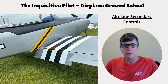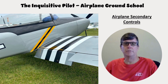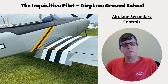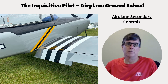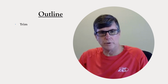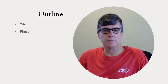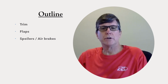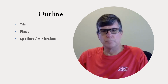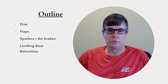During your check ride, you'll be expected to correctly use whatever secondary controls are present in the aircraft that you're using. As you progress as a pilot and you fly different aircraft, you'll need to know how to use additional types of secondary controls. Trim is used to relieve control pressures on the primary controls. Flaps improve the wing's performance at low airspeeds. Spoilers, sometimes called air brakes, are used in aircraft with very low drag to better control descents. Retractable landing gear improves an airplane's performance at cruise speed.